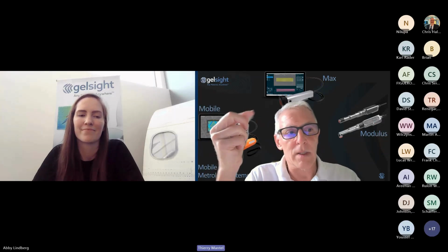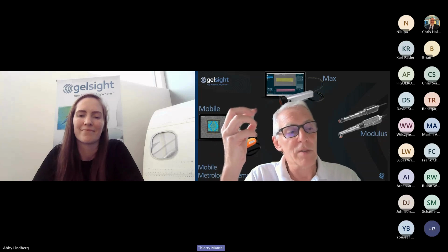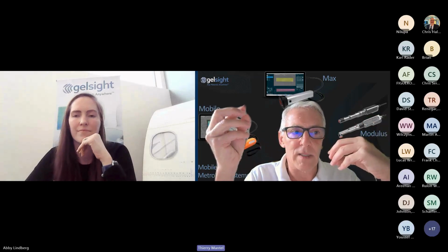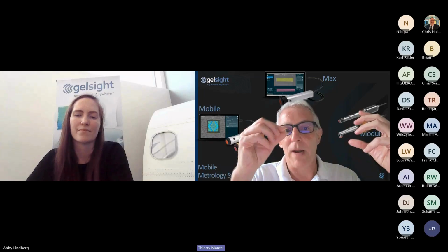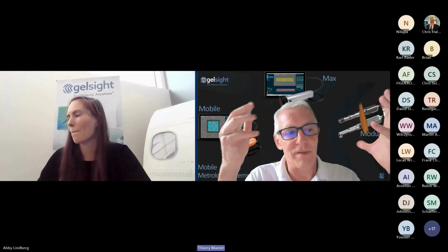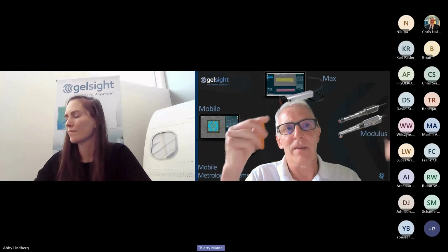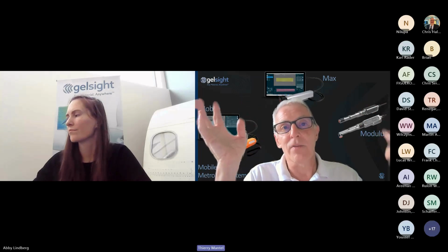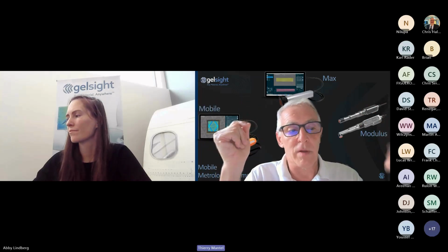And there is a second reason, with which I'm more familiar, especially in the aerospace industry: these tiny dents or tiny scratches can become micro cracks, which will propagate due to thermal and vibration fatigue, and this can lead to the failure of the part.